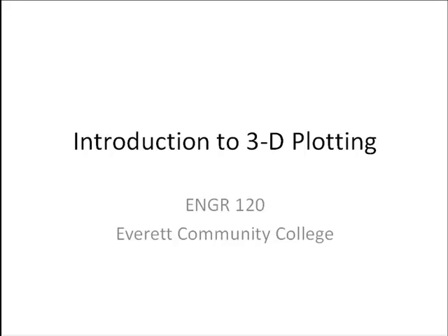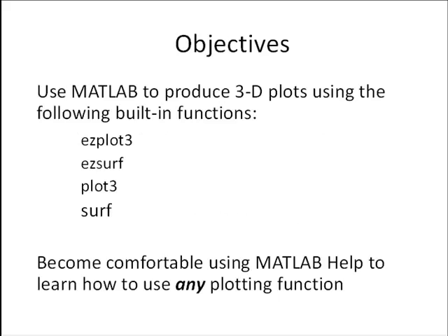In this video, we're going to get a brief introduction to 3D plotting. Our main objective will be to use MATLAB to produce three-dimensional plots using the following built-in functions: EZPlot3 and EZSurf, and we'll also get a general introduction to the whole easy approach to plotting functions.